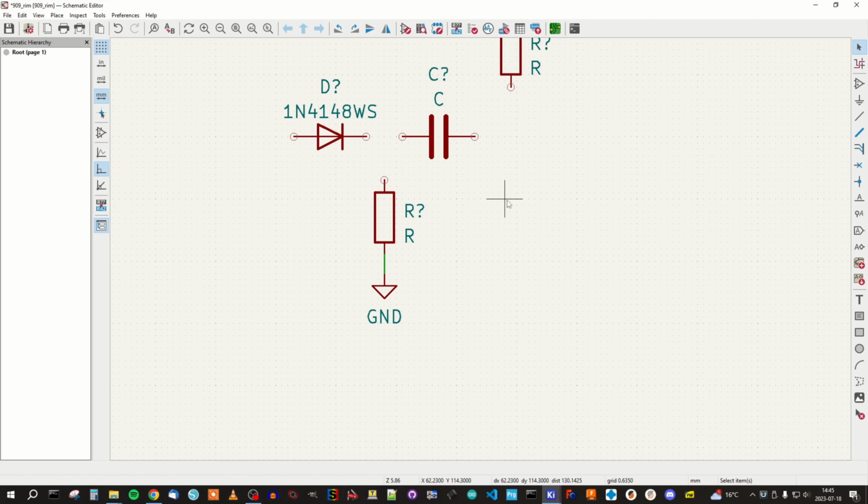And if you want to add a wire to an unconnected component, we just place the cursor above the unconnected end, or connection is maybe the right word, and then you see that the cursor changes to a pen. So this means that I can draw a wire now. So we will do that.